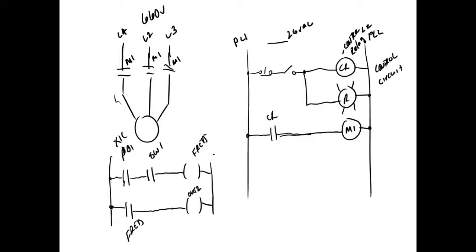Now, of course, when we wire this up, then we're using 2 outputs. One of them is going to turn on a light bulb, and one of them is going to bring in a motor source. And they called it a motor, but like I said, guys, you're almost never going to find a motor being controlled in the control circuit. It will be controlled by an output on the relay, right? Understand that?